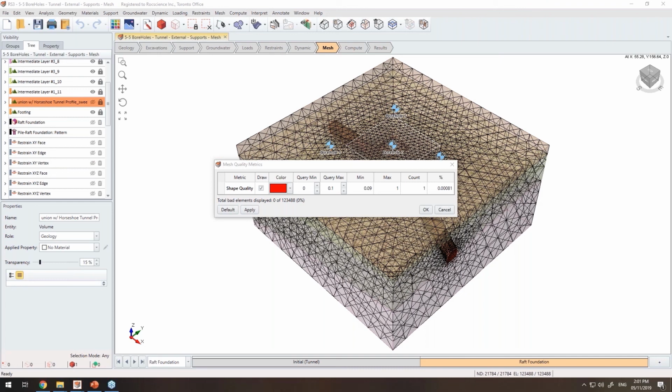How will the software deal with soil pockets in borehole manager? So the borehole manager is going to define your initial geology, but like the same example that we were looking at here, the tunnel was not part of the geology. The tunnel was another piece of geometry. I brought it in. It was interacting with all the other pieces. Then if you have any soil pockets, for example, you can define the geometry, and later on you can assign a different property to that piece of geometry.